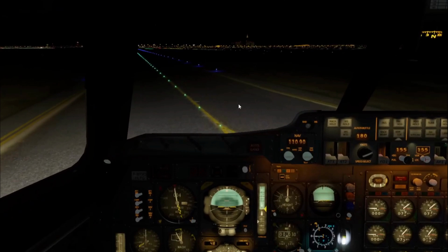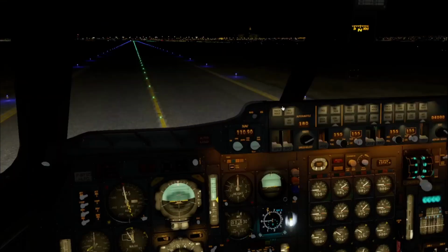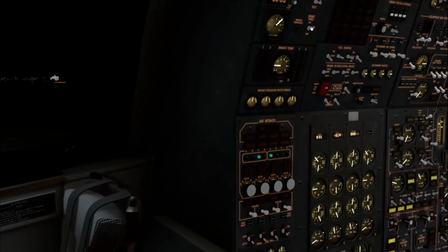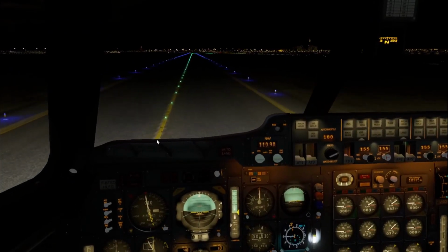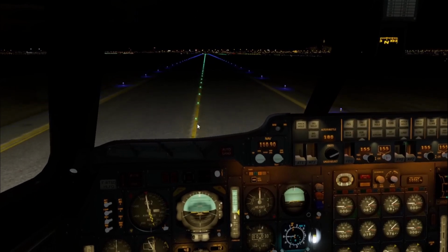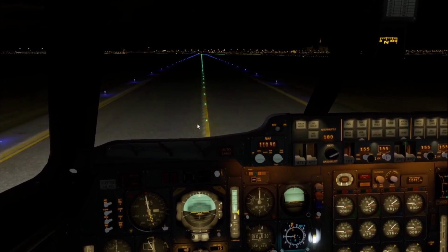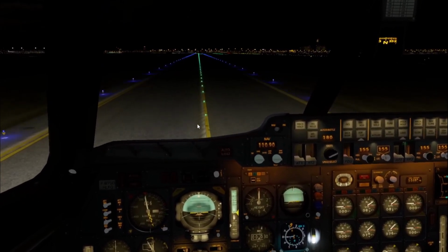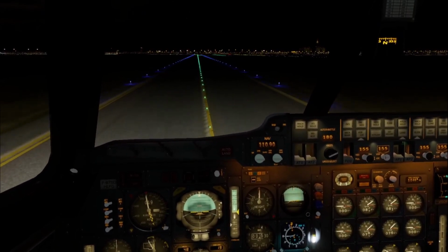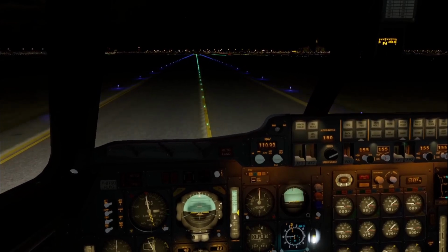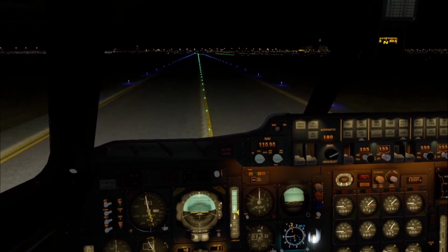To be faster, because this guy is rushing. And don't forget to set brake fans. We have more than 100 degrees temperature of the brakes, and currently the brakes are, let's say, very easy done and explained in a Concorde, because in the previous version there were more risk to have a puncture because of a high temperature. Now it's very friendly.